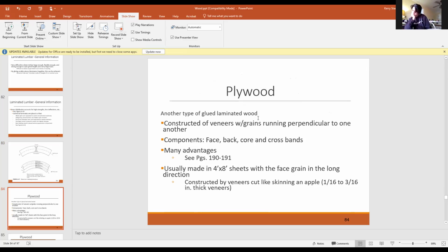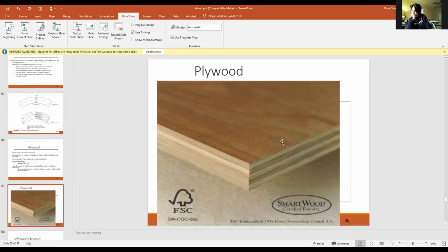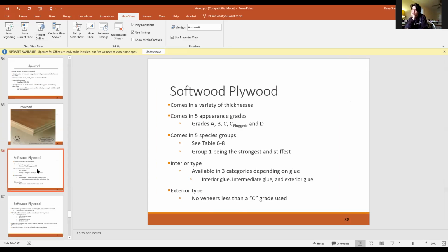So if you had a piece of plywood that had 5 layers, now you generally have a core on the inside, but you would have the outside running lengthwise, say long, most plywood's 4x8, right? And then the next layer on the inside would be perpendicular. The grain would be running 90 degrees to the outside. So that's kind of how that works, and it increases strength in both directions. All right, very good. And that's just showing you the layers. If you actually look at plywood that looks like a piece for furniture use, you can kind of see how the different layers are banded together there.